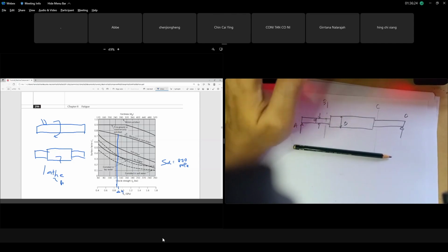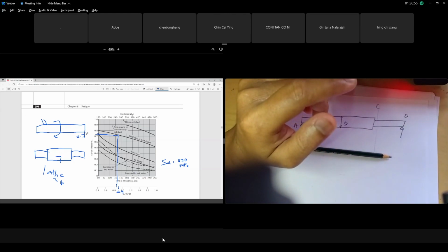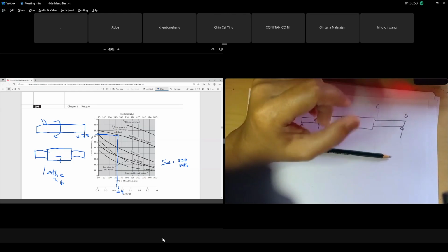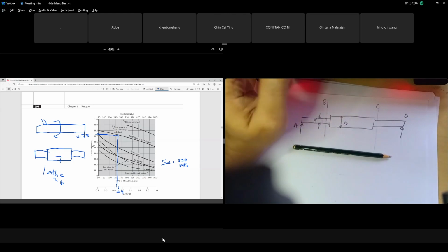But normally, most cases are machine, so you bring your 0.87 to this line, and make sure you use your ruler, because my hand is crooked. For example, you get 0.7, and you have to be accurate, guys. So you can predict this CS. Roughly what I put here, this middle one, between 0.7 and 0.8, is 0.75. This is 0.73. Clear, class? This is how you get your surface factor CS. Okay, class?